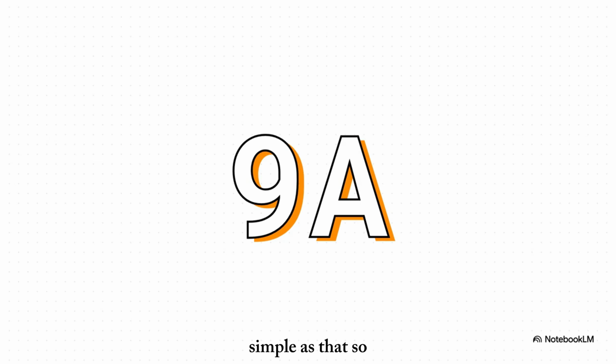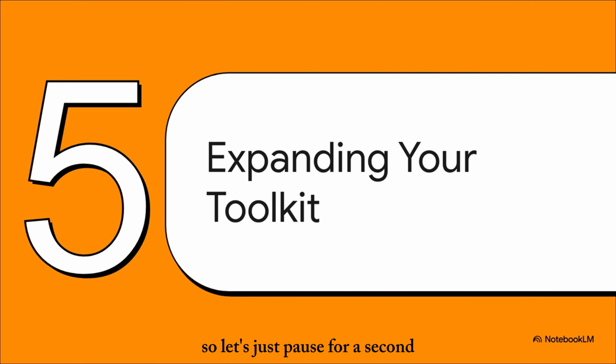Simple as that. So, what's the total current that has to come out of the battery to feed all these paths? Well, we just add up the flow from each one. 4 plus 3 plus 2 gives us a total of 9 amps. And just like before, this shows us another fundamental law, Kirchhoff's current law, which basically says that whatever current flows into a split has to equal the total current that flows out. Nothing gets lost.